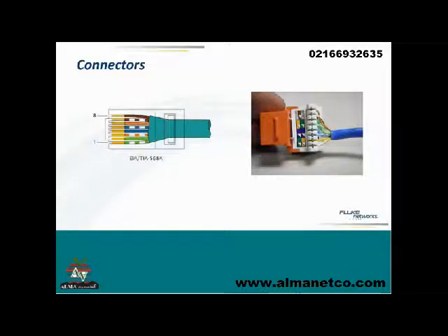Notice those cables, they're not twisted anymore, right? When they come out of the jacket and they go into that plug, they have to get untwisted for a little bit, and even that short little distance, which is much less than an inch, a centimeter or two, they're still in pairs, and there's going to be crosstalk because they're not twisted anymore. The same thing can happen on a jack, although you can see the person who put the jack together on the right there did a pretty good job of keeping them twisted all the way up to the point where they plug in. But then if you open that jack up, you'd see the wires inside, once again, the pins, they're going to be parallel to each other. They're not twisted anymore. So connectors are where most of the crosstalk comes from. In fact, that's where a lot of the engineering work has to be done to make really high-performance cabling systems.